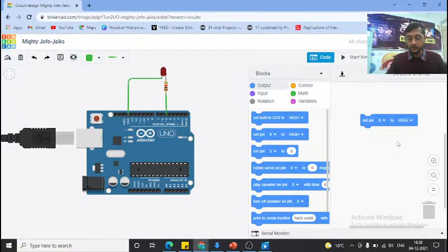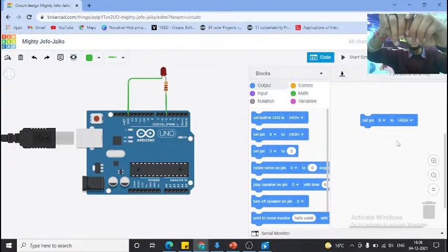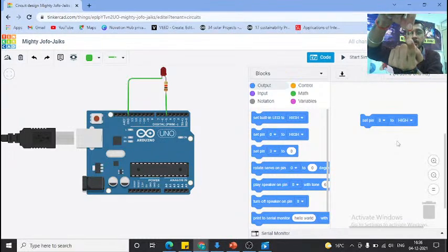If you want to see, I'll show you the physical part of the things. You can see this is the Arduino UNO hardware part, as I showed you earlier also. This is an LED. This is the physical LED part. As I told you, there are two leads in the LED. You can see it is visible. One is a long lead and the second one is a short lead. The long one is the positive one and the short one is the negative one.